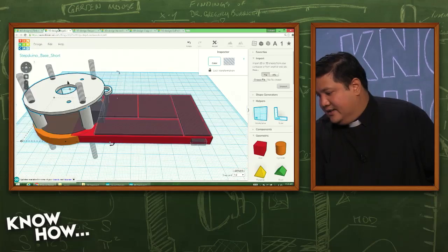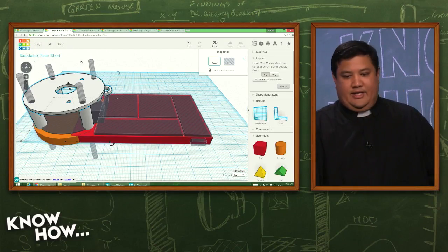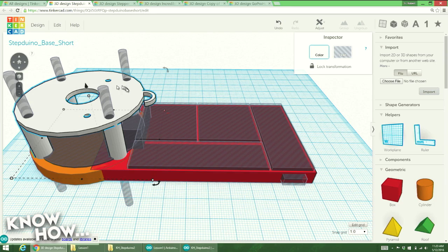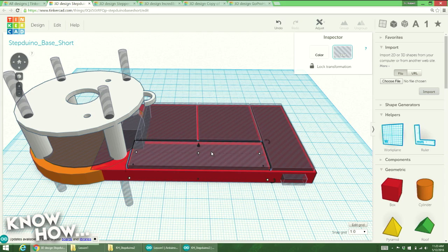All right, so the other pieces that I want to show you, this is the other important piece, is this. So this is the actual tray that I've created for this project. As you see, it gives me these 2 areas. This is exactly the right size for the driver boards that I've created. 2 driver boards? Right, because eventually I'm going to control 2 motors with this. This is where I would put the UBEC. So the power supply actually goes in here. And then this is where the Arduino goes. So I'd be using an Arduino Nano. Yeah, I was going to say, that's not big enough for a regular Arduino. No, right. But again, it controls it just fine.